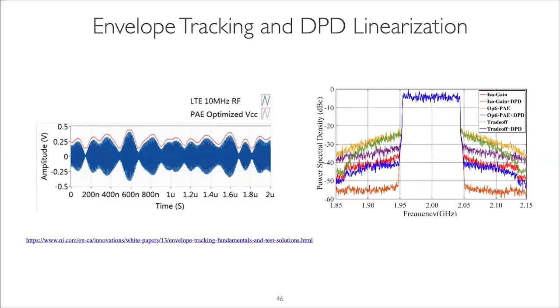What envelope tracking means is you're modulating, or controlling, the drain bias. You're not leaving it on the whole time. You're modulating it so that when the device needs that drain bias, it uses it efficiently. It's not just totally on. Therefore, when you have low power, the efficiency and the gain is very low. You're utilizing this modulated bias to optimize the performance.